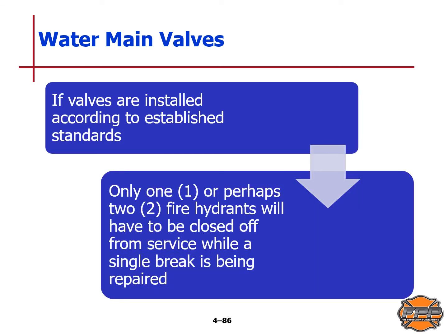Butterfly valves are tight closing. They usually have a rubber or rubber composition seat that is bonded to the valve body. They are non-indicating, so they require a special type of valve key. And the principle of operation provides satisfactory water control after long periods of inactivity.